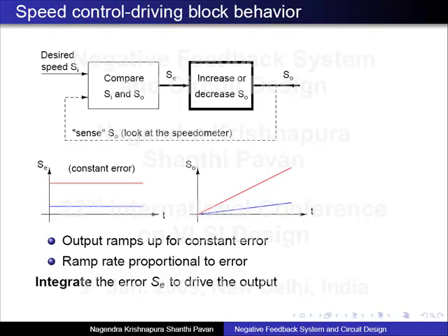It can be implemented in many ways. And how are you able to tell positive feedback? No, positive feedback tends to drive the error up. It's not the output itself. The output can go up or come down, but the error between what you want and what you get goes up in the case of positive feedback and comes down in the case of negative feedback. In an ideal negative feedback system, that error is 0.